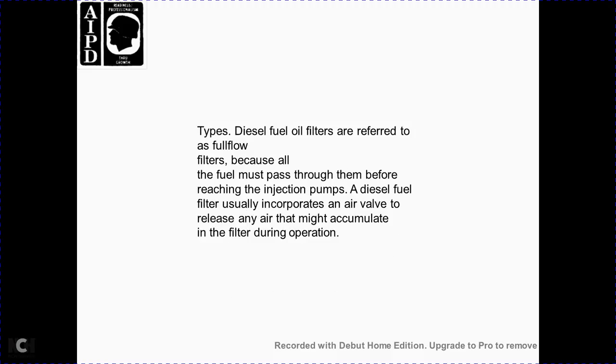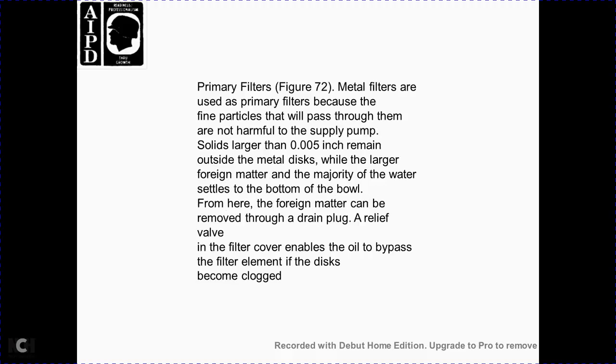These types of diesel fuel oil filters are referred to as full flow filters because all the fuel must pass through them before reaching the injection pump. The diesel fuel filters usually incorporate an air valve to release any air that might accumulate in the filter during operation. The primary filter, figure 72.